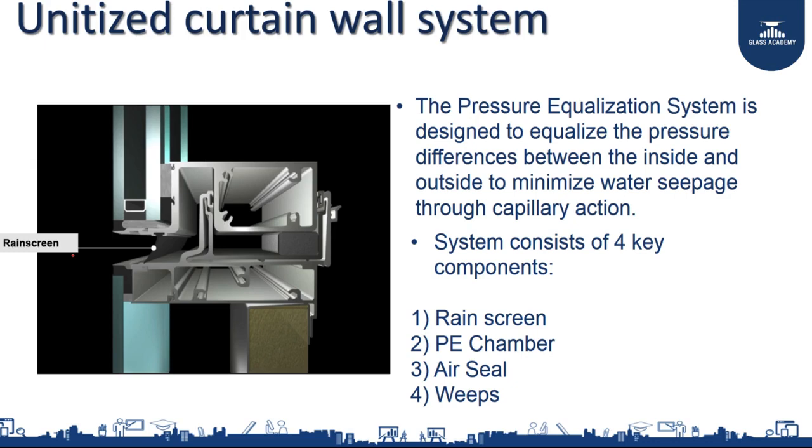So, you design the system to let the air pass through, but not to create a heavier suction inside, because internally, as it is weak, there is always a tendency of pulling anything inside. While you design a system, the first 4 factors you have to see are 1, 2, 3, 4, what is written here. A rain screen. If there is wind and water together, they will find a way into your building. So, you want to shelter the building against wind and water.